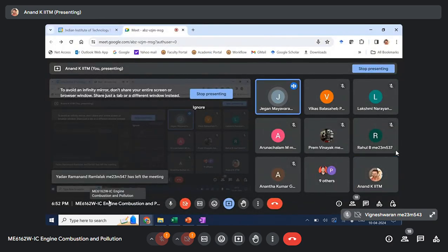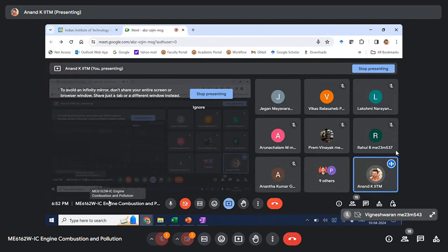Sir, this over mixing, in any case, due to this ignition delay, finally the fuel mass will accumulate and it will go for a knocking effect, no sir, like instantaneous combustion. Knocking is okay. So what you are saying is when delay time is longer, there is also knocking. Correct, sir. So in any case, my hydrocarbon is getting burnt, because the HC formation more or less should be the same irrespective of the accumulation, because only the phase is getting different, no sir.